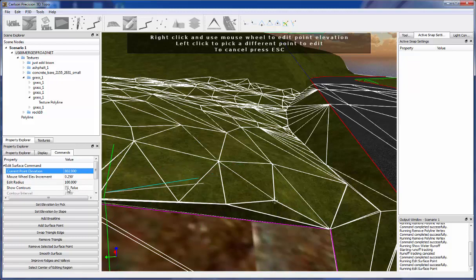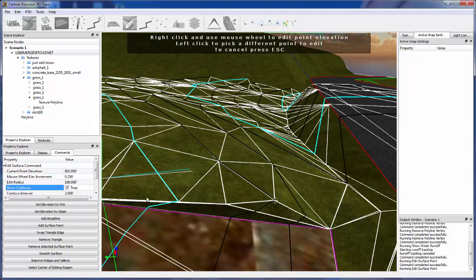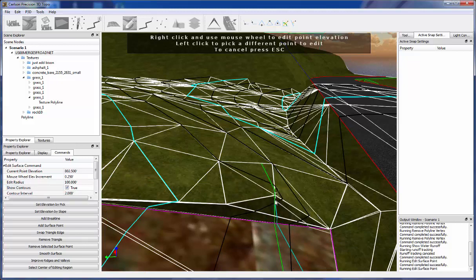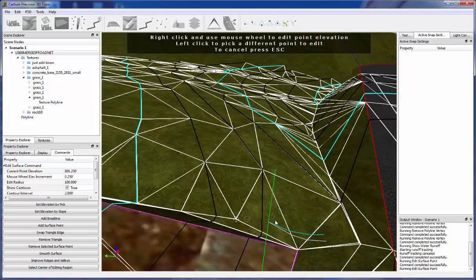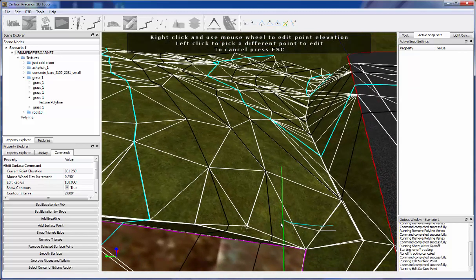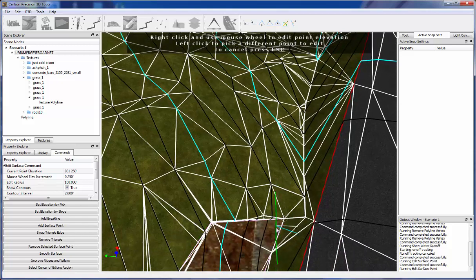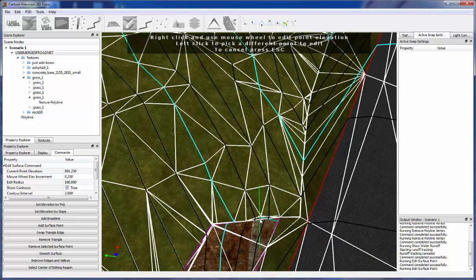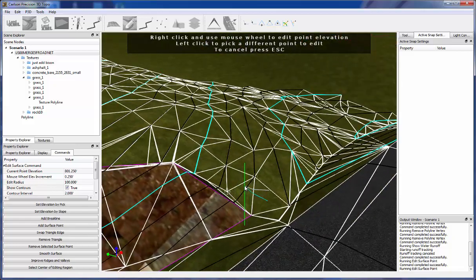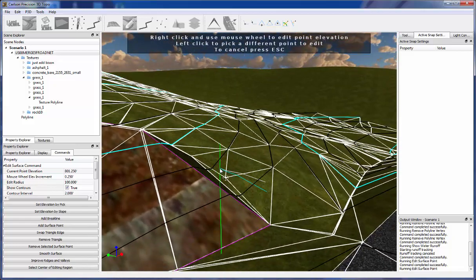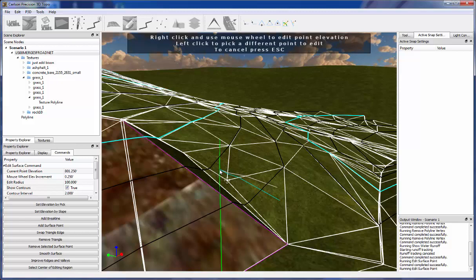I can show contours so that as you make modifications to the surface, you'll notice that the contours change and are modified dynamically to give you that instant feedback as to what your design surface looks like. So you basically get the best of both worlds. You get to see all your triangles and faces in this CAD perspective of the 2D plan, but then also we allow you to rotate that into 3D so that you can get more detail as far as what it looks like, and you're in a multi-textured environment, which gives you additional visual cues